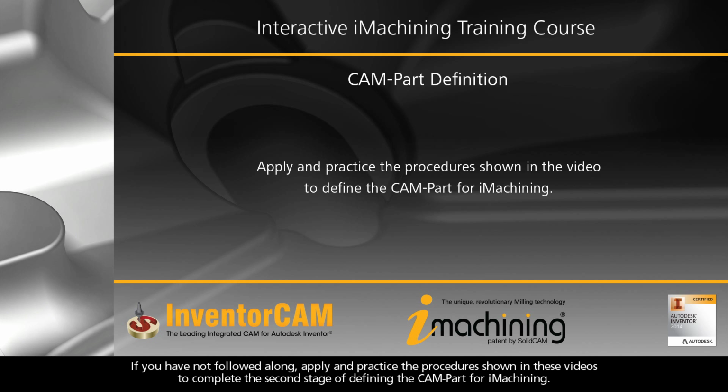If you have not followed along, apply and practice the procedure shown in these videos to complete the second stage of defining the CAM part for iMachining. Remember, the procedures for completing this step include defining the machine and work material parameters for the iMachining database.